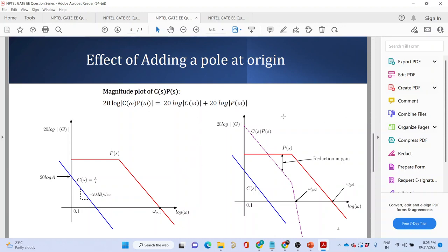Sorry, I was talking about the Bode plot. If that is so, what you observe is that at steady state there is only the DC component, right? There are no other frequency components. There is only one frequency component, the DC component. So where are the higher frequency components? The higher frequency components appear in your oscillation during the starting of the system. At the start, you see the sudden rise, and then it oscillates and settles down.